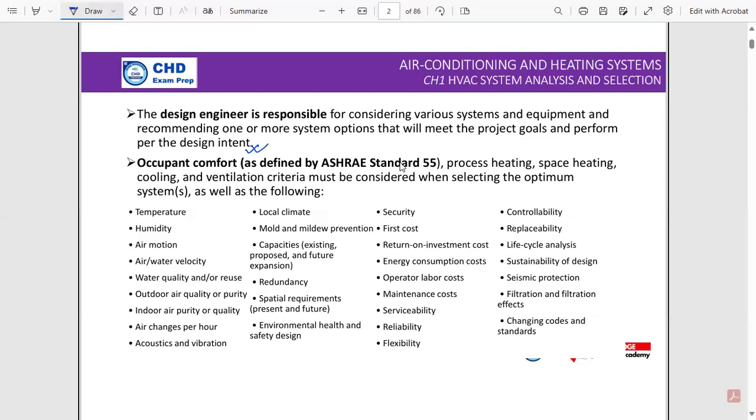Okay, let me make it very simple for you. At the beginning of the project, the HVAC designer must ensure the system that is required for the project. So the HVAC designer will study the project and offer to the customer these sets of solutions. For example, if I go to a commercial project, I study the project, I offer to the customer that either you can go for a VRF system or you can go for a chilled water based system. And depending on the various factors, the customer will make the call. So the system selection will come at the very beginning of the project.